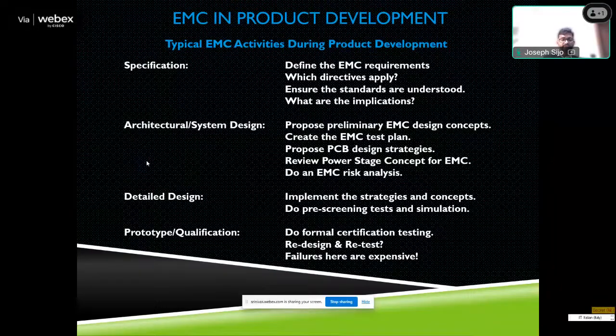They will do design reviews 1, 2, 3 with different test plans, then the manufacturing trial, pilot production and final manufacturing trial, and finally mass production. Before final manufacturing, especially in the manufacturing trial and pilot production, they always check how well it complies. I'm talking only about the EMC topic.